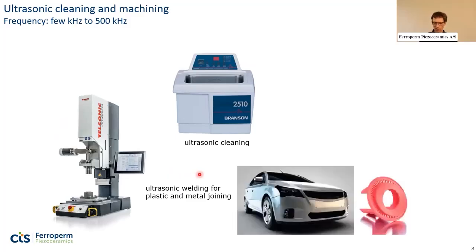So an example where this is used is for the attachment of these plastic mounting devices to the bumper of a car. So these inserts are actually for holding distance sensors, acoustic distance sensors for controlling whether you hit something with the car. And these fixtures are actually attached to the bumper, just using this ultrasonic welding for a very short time, just less than a second.